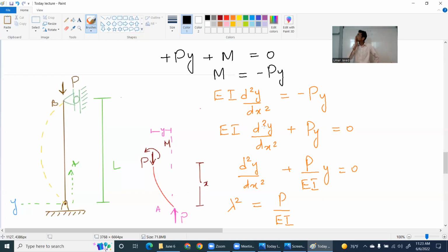So how can we decide that the moment acts like this? Yeah, that's what I'm saying. I cut it, I throw the right chunk away, and I saw my statics classes. They told me when I cut from the right, I put an anti-clockwise moment. Does it ring bells? In statics, that's what they told me, right? I used to throw the right chunk away.